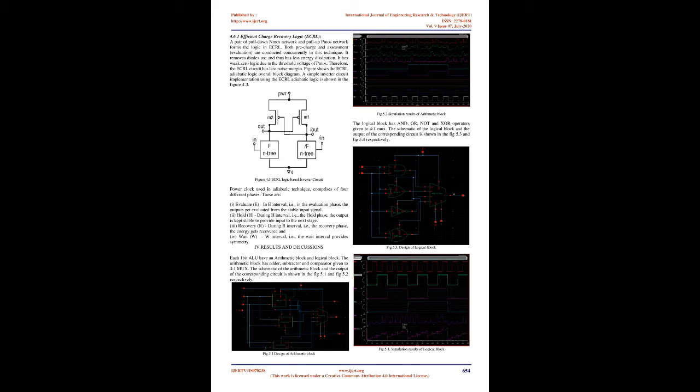In enhancement mode of MOSFET, when there is no voltage on the gate terminal, it does not conduct. Unlike the depletion mode, in enhancement mode, the device conducts better when there is more voltage on the gate terminal. The main aim of the MOSFET is to control the flow of voltage and current between the source and drain terminals. A high-quality capacitor is formed by the gate terminal.